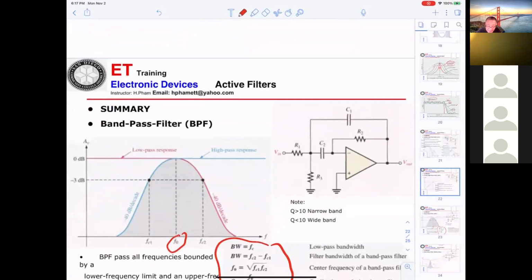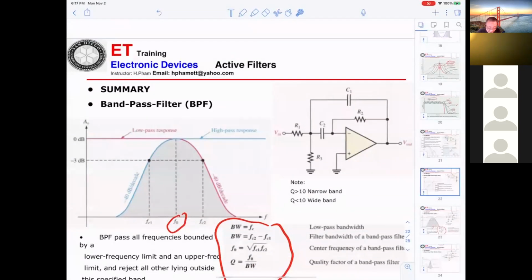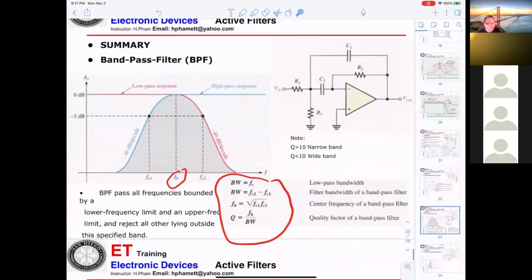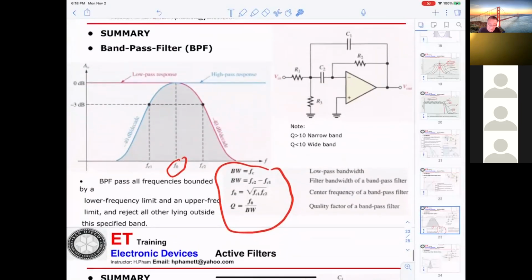They can ask you what it is here. Then you have to say that is the output of the band pass filter. Okay, if they want the bandwidth, then the bandwidth will be equal to FC2 minus FC1. Okay, if they want to calculate the quality Q, that means how good the filter is, it equals F0 divided by the bandwidth. Okay.